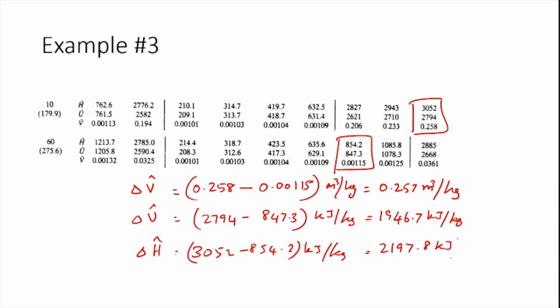In addition to all this, we have also been asked to find the dew point or the boiling point for the superheated steam. So, dew point would be the point at which condensation happens. Here the superheated steam state is 300 degrees Celsius and 10 bar. So, going back to these values here, you can find the boiling point as 179.9 degrees Celsius, which is also the dew point or the point at which condensation would happen.